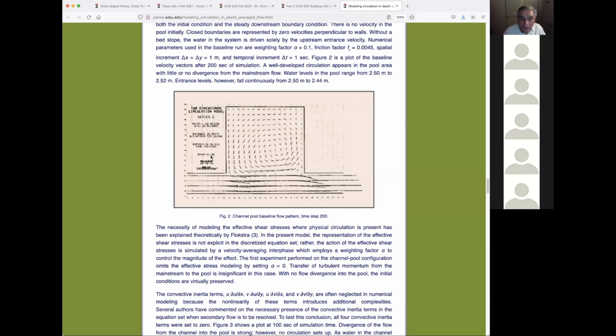I was trying to convince one of our students, I had a meeting recently overseas, I have some students overseas, that you got to strike a middle ground. You cannot make the mesh too fine or too coarse. If it's too coarse, it will be inaccurate. And if it's too fine, it will blow up. But that was something new that this gentleman had not heard before. I said, yep, it will. I can show you. You can test it.